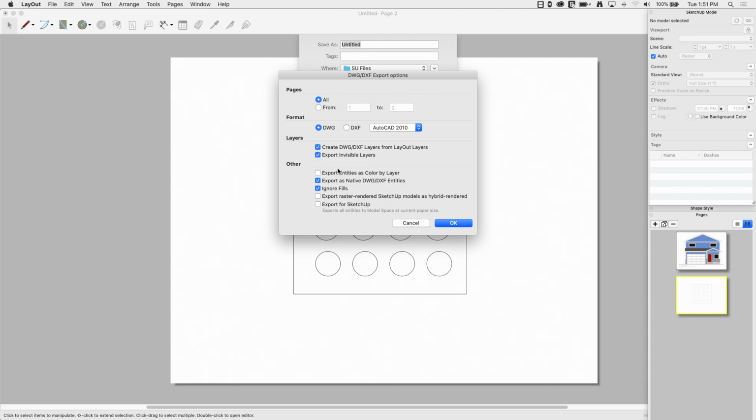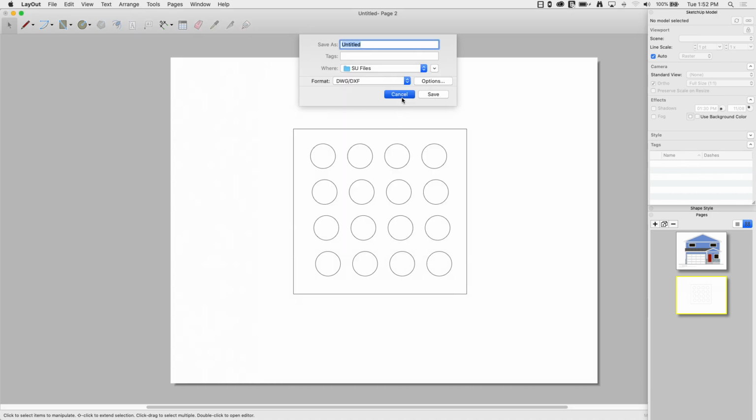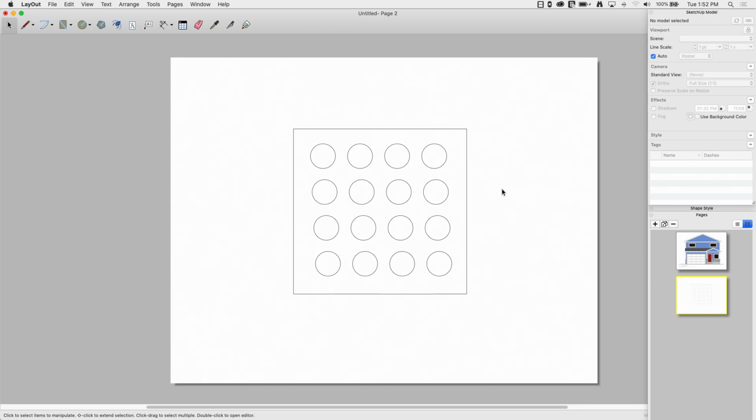You should always look at options when you export, but specifically, if I want to take this geometry and export it as a DXF for use elsewhere, I want to be sure to set my presets correctly so that I get out the file I'm looking for and not some weird jumble of lines at a scale that is going to be unusable.